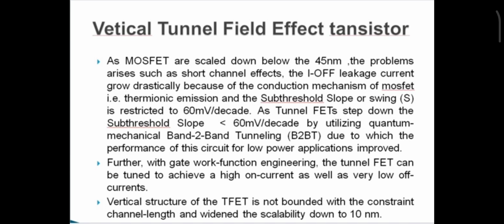Further, with gate work function engineering, the tunnel field effect transistor can be tuned to achieve a higher on current as well as low off current. In the proposed structure, I will do the gate engineering by introducing a triple metal gate to improve the on current. The vertical structure of the tunnel field effect transistor is not bounded by constrained channel length and widens its scalability down to 10 nanometer. This means in the case of vertical TFET, we can scale down the channel length up to 10 nanometer.